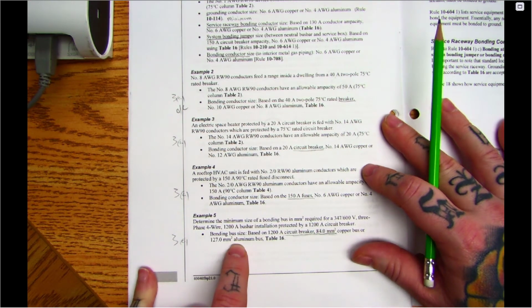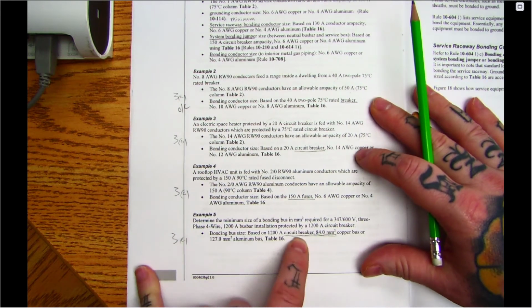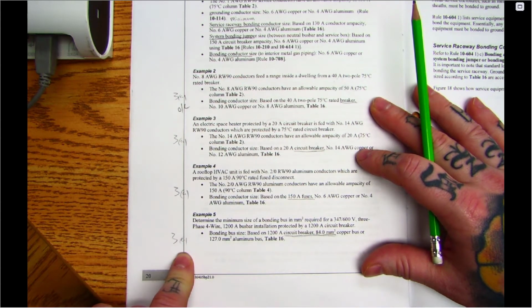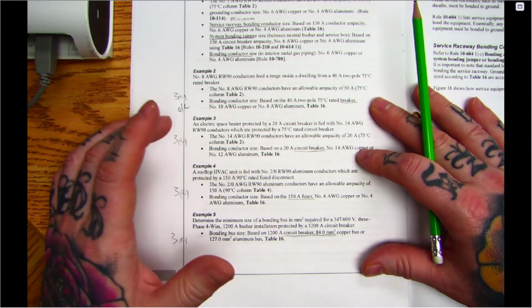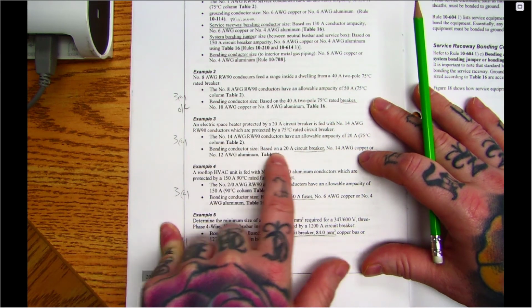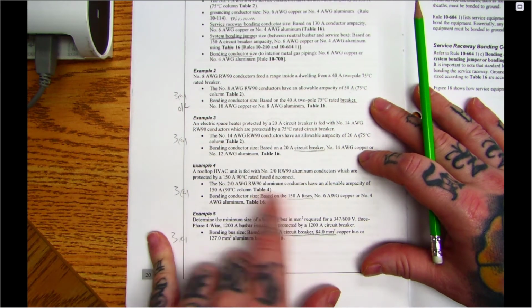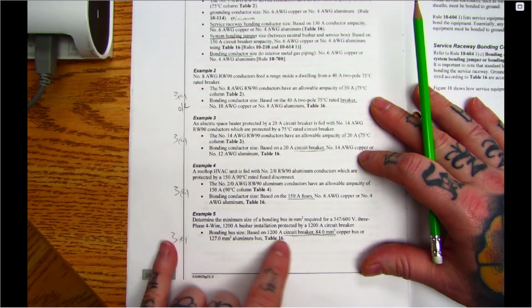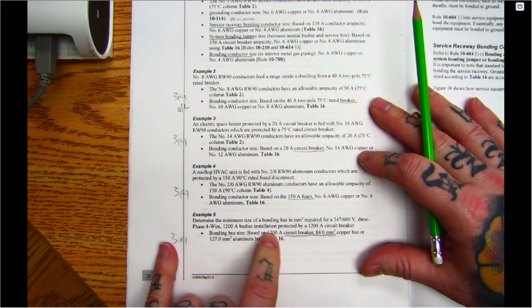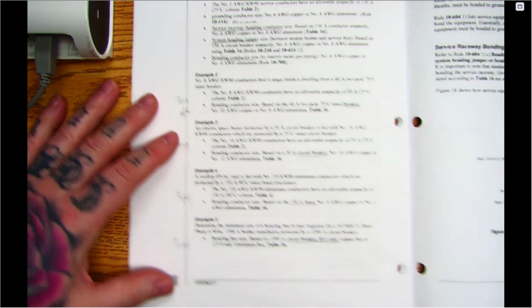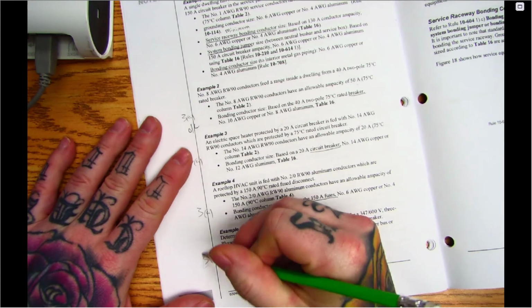This one doesn't really say what it is, but I used 3A for these as well too. 3A is basically bonding other than your service, and that we're going to use the overcurrent. Okay, but they'll say bonding conductor based on the breaker, based on the fuses. So this actually could be a system, so they could be using the breaker for that, for the system bond. Yeah, that would be 1 here instead of 3A.